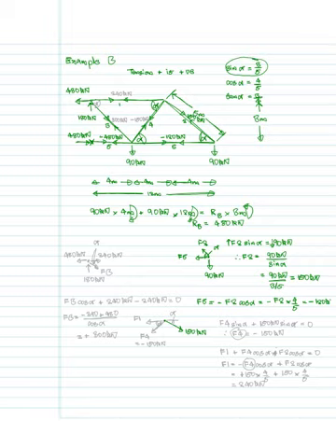We also know that that value there is going to be F4, and that value there is going to be F1. Drawing them all in the direction of tension is positive for the members, i.e. make sure the arrows are consistent with the arrows we can see on the truss.